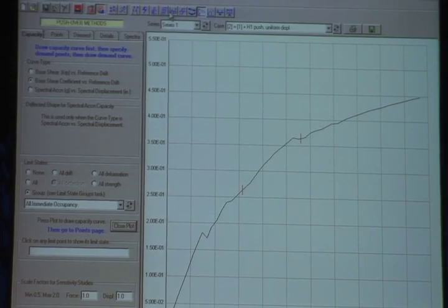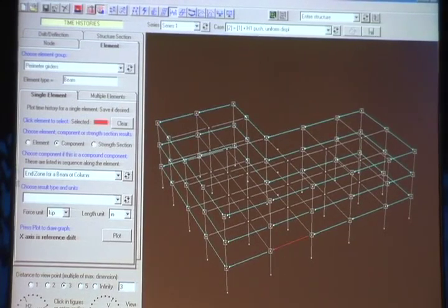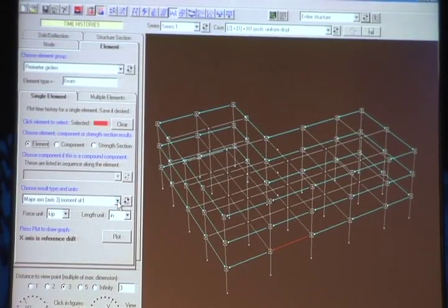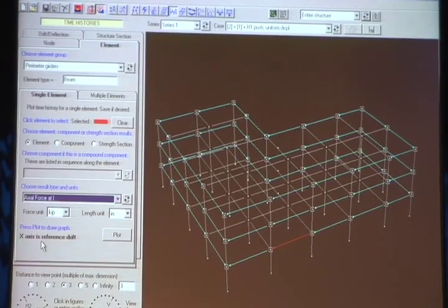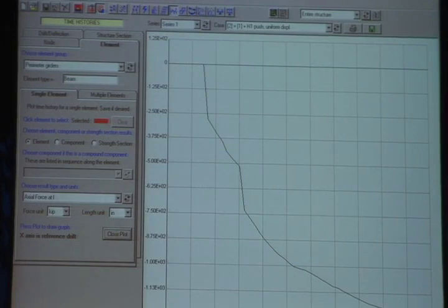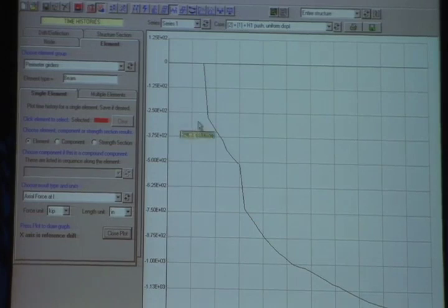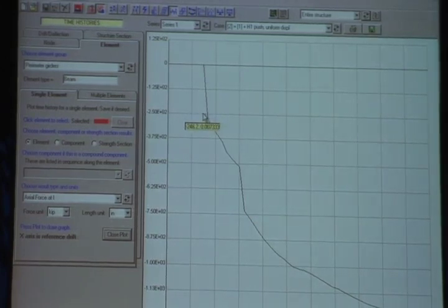One thing I'm going to do is actually come to this beam, and I'm going to look at the axial force in the beam. But I have a rigid floor diaphragm there, and the beam cannot grow in length, so in fact it's fully restrained. So instead of growing in length, it goes into compression. And it goes into rather a large amount of compression, so this analysis doesn't look very good. So as a second thing, I said, okay, well, let's put in a PM hinge there such that instead of just the axial force being allowed to grow without limit, it'll be limited by the PM hinge.